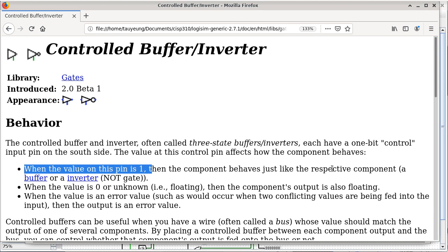So you would go from one signal to fan out into like 8 of these buffers, and then each output of the 8 buffers will go to 8 actual destinations. So you can now control the fan out and limit it to 1 to 8, instead of 1 to 64, which may not be physically doable.